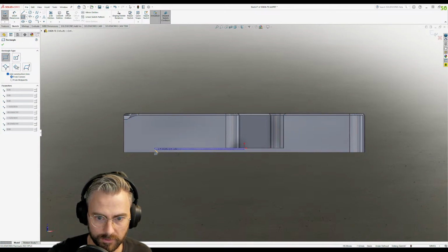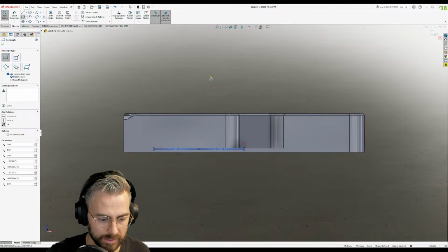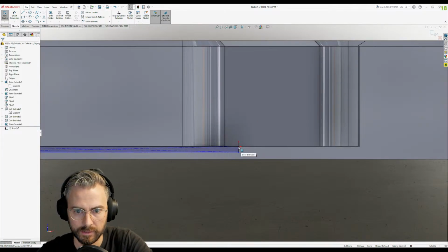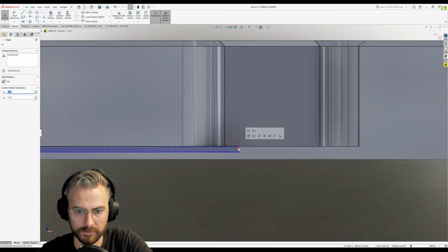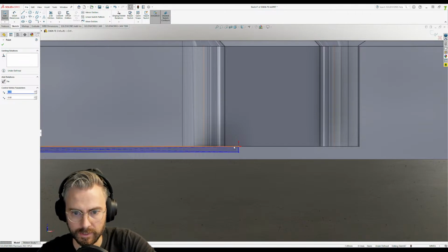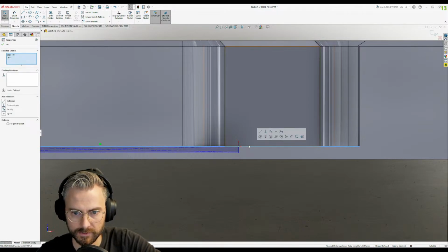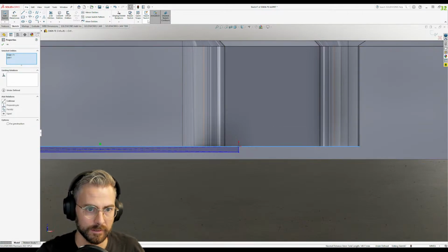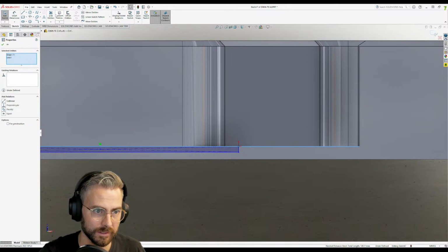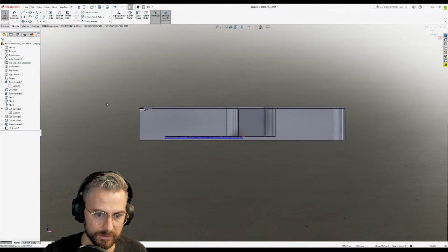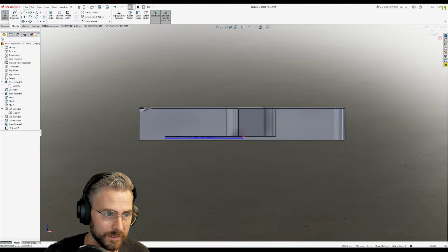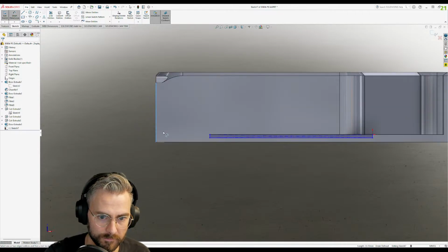And this is going to be roughly where our PCIe is. Actually, we're going to get rid of that. That's not going to be coincident on that. But this is going to be coincident on that side because that's where the PCIe slot is. So we're going to make that collinear. So that's defined there, but we're going to dimension that to there is 45 mil.